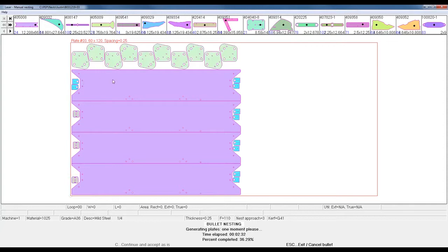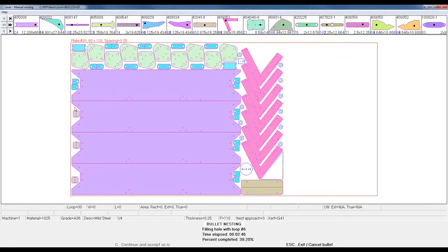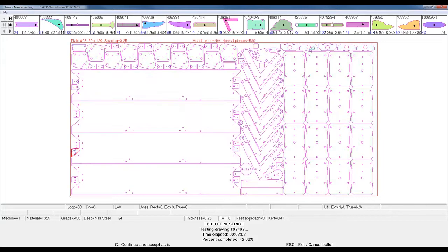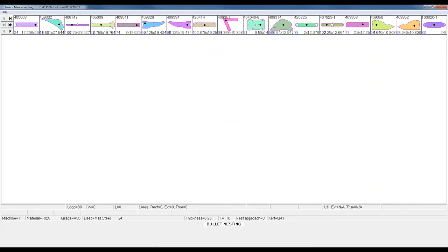We're getting into sheet 3. You can tell it is also trying to go through these parts in a way that makes sense for unloading them. So the parts that were filled on here are completely different than the original first 2 sheets, but you'll notice that it's not using ones that it used before because it's already consumed them. It's always trying to put parts and fill them, and once it's done with them, you could unload those parts, put them on the pallet, etc. Oh, that's a good example back there of some more automatic common line cutting. And because of that, it looks like it got some extra parts up top that you wouldn't have got normally, which is a perfect example.